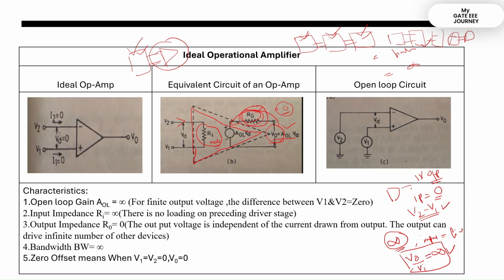It won't depend on the resistance of the output circuit. Why? Because it is 0, the output voltage is only dependent on the output load current, and that load current will not be changed with the changing of this output resistance.